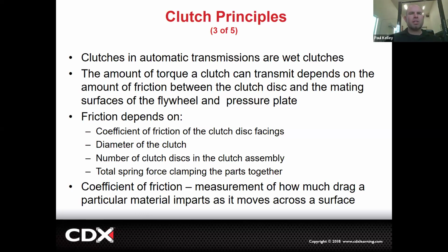Right. So it's kind of similar to brakes, but brakes are a little unique in the sense that if you really jam your brakes really hard, you're still having to do the same amount of work to slow it down. But it would actually be worse if you're constantly tapping your brakes. If you let off the gas, just let it coast if you can. If you have to hit the brakes, no problem, but that is wearing your brakes down. It's kind of like the clutch. The more you can leave that pedal alone, the longer it's going to last.